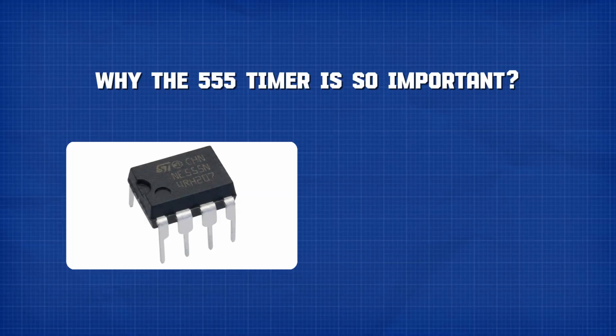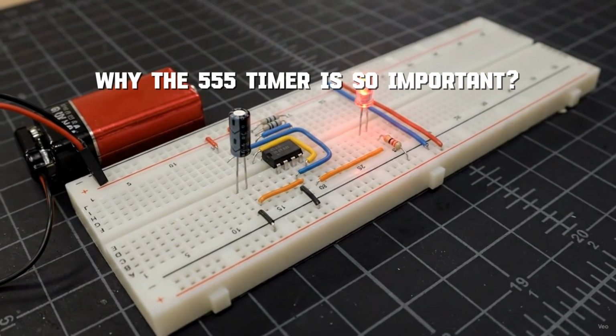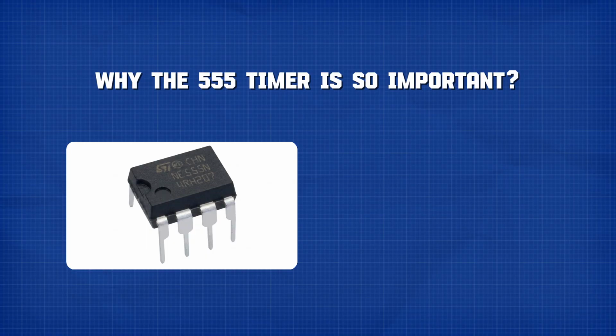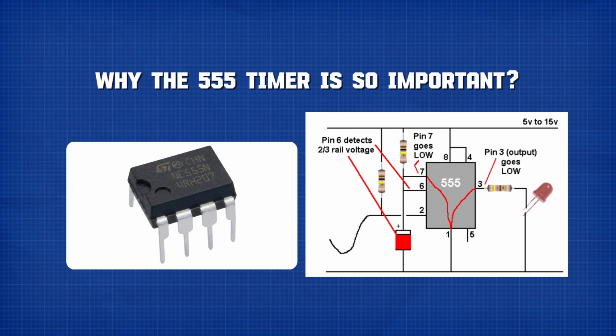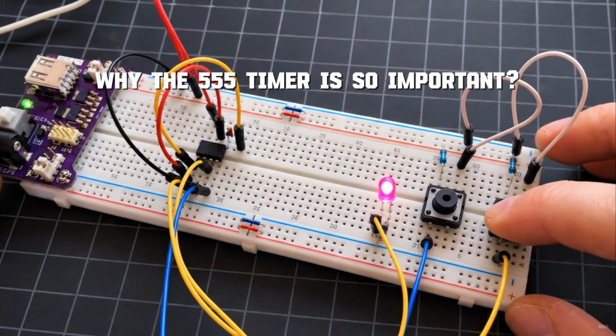Why the 555 timer is so important. Now, the reason the 555 timer is powerful is not because it is big. It is powerful because it can replace many small timing circuits. Before, to make a timing circuit, you may need transistors, resistors, capacitors, and other components arranged in a complicated way. But with the 555 timer IC, most of that work is already inside the chip, so instead of building the whole timing circuit from scratch, you can use the 555 timer and just add a few external resistors and capacitors to control how fast or how slow it works.